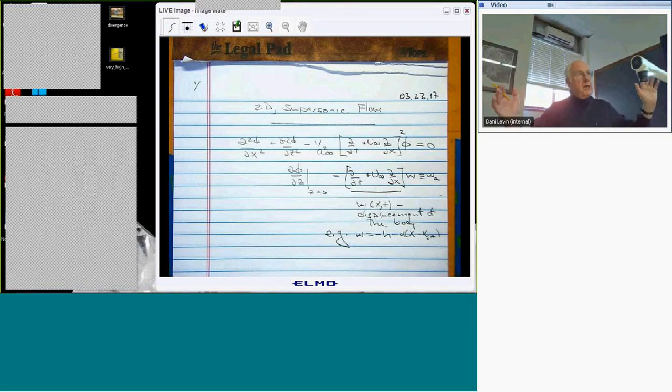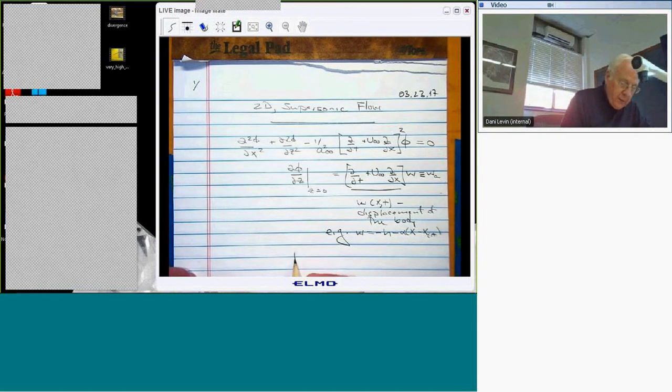The aerodynamicist thinks that the motion of the airfoil is given, and she's going to compute the pressure on the airfoil and give it to the structural engineer, who's a lesser mortal, so that'll be a man, right? And therefore, the aerodynamics is done, right? Okay, and then finally, the pressure, actually the perturbation pressure, is minus rho infinity, the free stream density, again times this time derivative, the substantial time derivative, times phi.